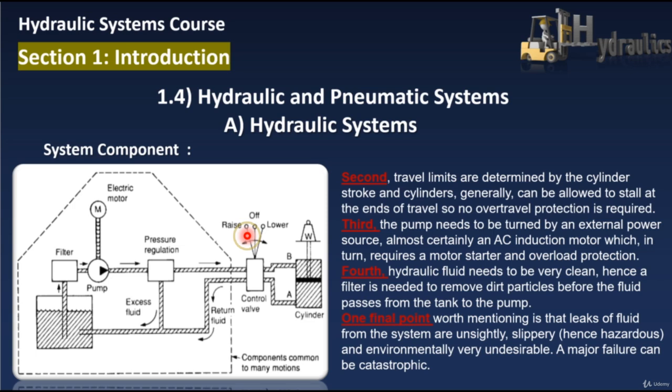The fourth point is that hydraulic fluids need to be very clean, and hence a filter is required to remove all dirt particles before the fluid passes from the tank to the pump. If fluid with some contamination is introduced to a pump, it may destroy the pump. One final point worth mentioning is that leaks of fluid from the system are unsightly, slippery, and hence hazardous. A leak of hydraulic oil may cause safety concerns and is environmentally undesirable, and a major failure can be catastrophic.